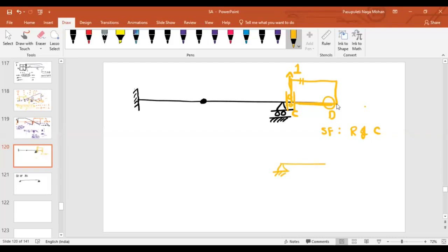What if, imagine, in the same case, there is a support like this, what do you think the deflected shape might be? Will it be the same as previous? No, sir. Why? Because imagine this is a joint D. At D there is a support. Will it allow any vertical deflections? No. That's why, as it will allow the rotation, the deflected shape might be like this. Because as it is a support, it won't allow any vertical deflection. So if you correlate these two, you might get clarity.